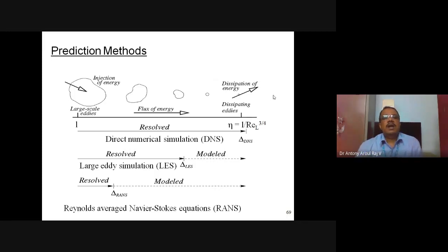So you have to use a small time step and solve a transient problem like what we have seen previously. And you know that in turbulence we have eddies varying from smaller eddies to larger eddies, because in turbulence the energy is given from the larger eddies to the smaller eddies. That is called the energy cascade. That is the physics of turbulence. So from the larger eddies energy goes to the smaller eddies, and that is what we see in a turbulent flow field. If you are going to model that, you have to model everything from the larger eddy to the smaller eddy as a transient problem.